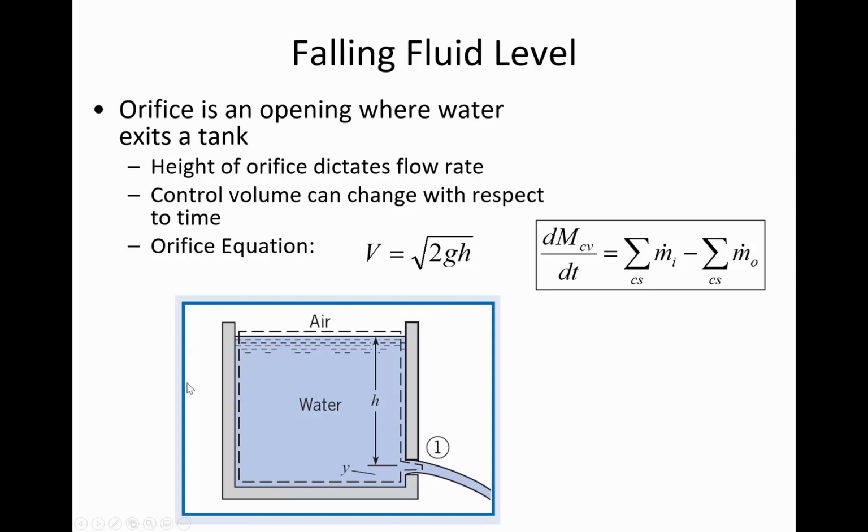Looking at this picture, it's clear there's no flow in, there's only flow out. So the liquid level is going to be getting progressively lower, and as it decreases, the pressure just outside of the orifice is reduced. And if the pressure is lower, then the velocity of the jet is going to decrease.